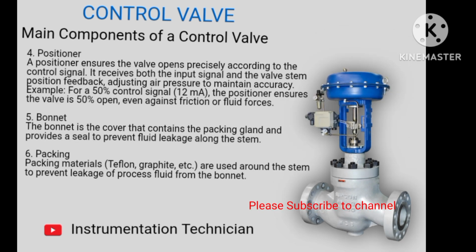4. Positioner. A positioner ensures the valve opens precisely according to the control signal. It receives both the input signal and the valve stem position feedback, adjusting air pressure to maintain accuracy. Example: for a 50% control signal, 12 mA, the positioner ensures the valve is 50% open, even against friction or fluid forces.